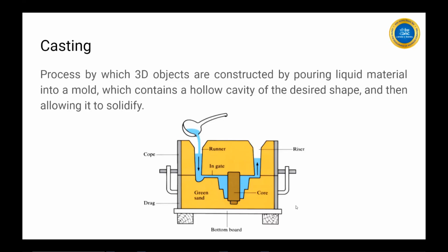That is a minimum, I am saying. So it would be justifiable only if you are able to make a mass number of parts, thousands and tens of thousands of parts, then only the mold price would be justifiable. If you are making something in a small quantity, casting or molding is not the right manufacturing process to approach.